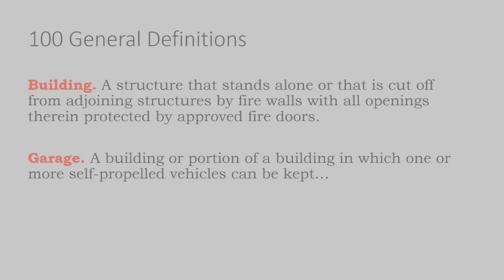And so the question is, you might get into an issue where is the equipment, like, is a ground mounted solar array considered to be on a building or not? Now, there's different requirements. If this is on a building, you have to do rapid shutdown. If it's not on a building, you don't need to do rapid shutdown.